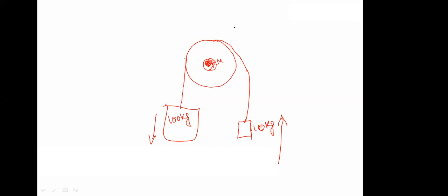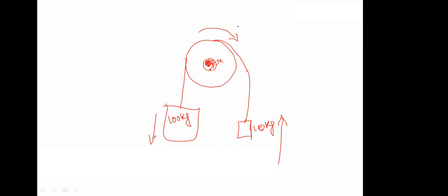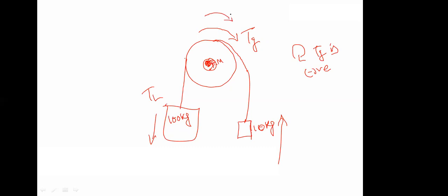Yes, sir. Now the motor has to provide an opposite torque or not. So the load torque is TL, negative, and the TG is clockwise. So if the TG is clockwise, TG is negative, right? Now what is happening? If you are saying that the motor should rotate in the clockwise direction, TG, then what will happen?